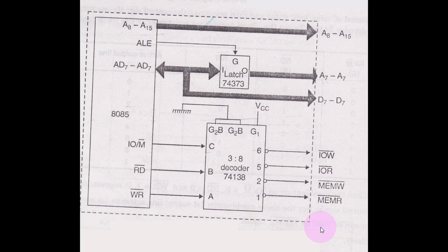So this is the complete structure which is known to us as of now for a microprocessor. This is your microprocessor, and you have interfaced a latch to it for address latching purposes on AD0 to AD7. So this is AD0. This should have been AD0. It's a misprint here. This latch is used to address the lower byte of the address, the complete address that you have got, and this is the data section. And this decoder is used for converting these control signals into these control signals, right? So you do not have to monitor these three signals. Your work will be done in these four.